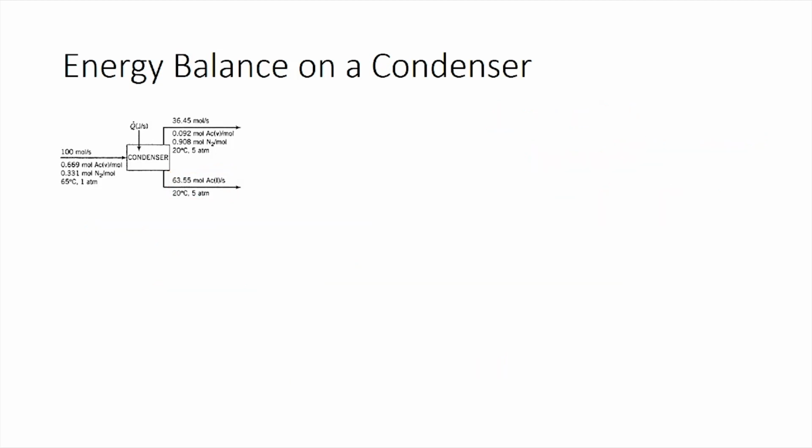The next step is to construct an inlet outlet enthalpy table. Let us look at how the table should be constructed. We first have to write down all the substances or components which are there.